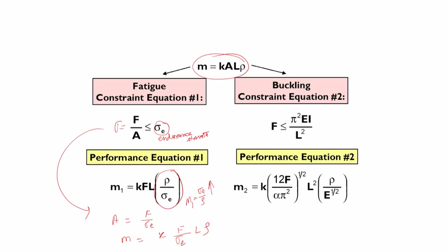Okay. Second one, you can do the same way I have done earlier for that circular beam. Only a small change that you can do is that the I here need not be exactly circular. So, the I generally we take as pi r to the power 4 by 4, right. Instead of that, we will keep it as a factor alpha and put it as pi square by 12 r to the power 4.